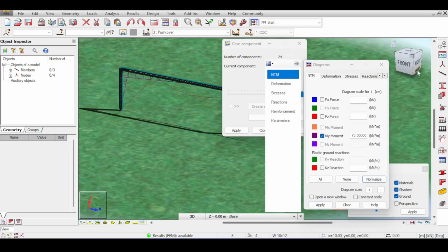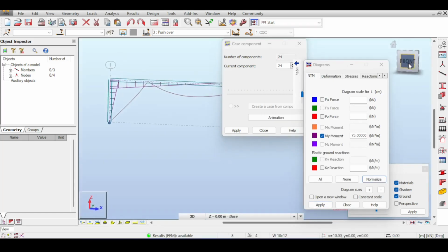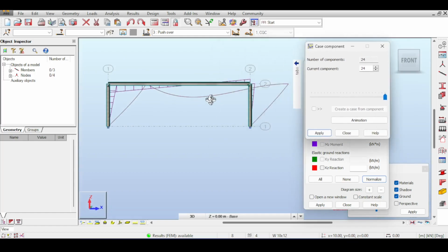I want you to see this because I wanted to see my thinking process. I'm surprised. I thought it should be unstable, but it isn't. It isn't unstable because what happens here is not that the entire fixed support snaps. What happens is that the ability of the point to resist moments snaps, which means that suddenly your fixed support becomes a pin. And this is perfectly stable for a pin structure. And this is the reason why it didn't get